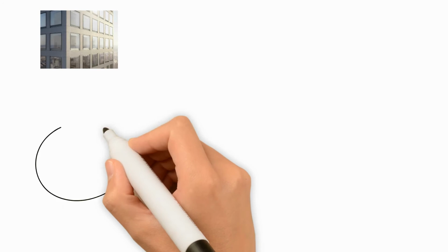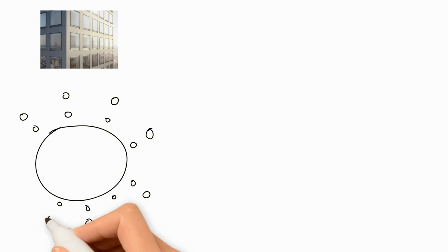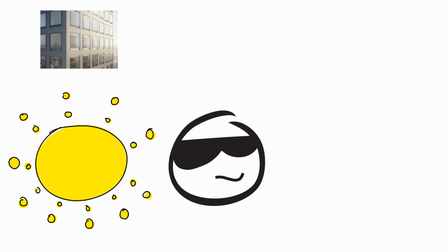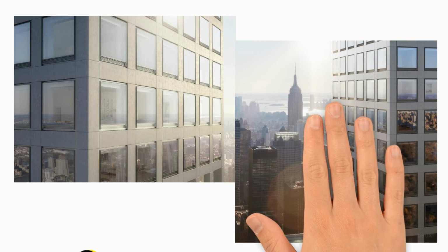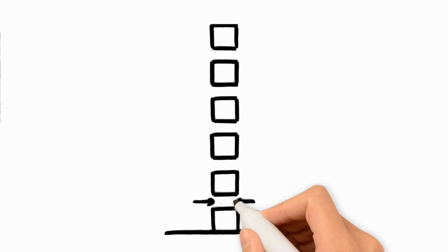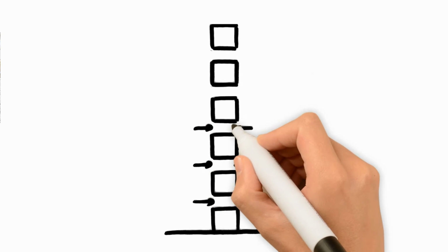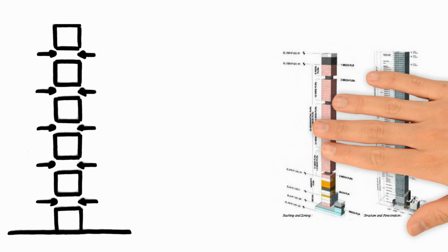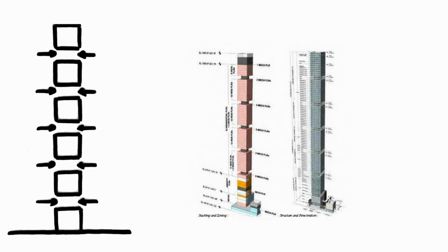The tower is identical on all 4 sides. Although this goes with the architectural strategy, it does not consider the position of the sun and the effects of heat gain. Solar shading should provide a better environmental solution, but the associated wind effects may make them invisible. 432 Park Avenue helps reduce the length of ducts in the mechanical ventilation system and thus the electrical energy used by having air intakes at each service floor rather than the ground floor.